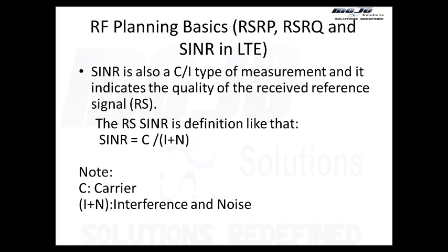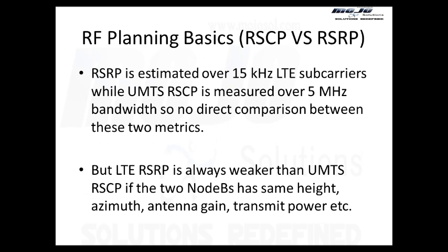Anything below 5 is considered bad. Sorry, SINR is not measured on a linear scale, it is measured in dB, on a logarithmic scale, but the good values for SINR are considered to be 10 or above. In the whole of our discussion, or practically in the field, you will hear SINR. You will hardly hear RSRQ being discussed for a signal.